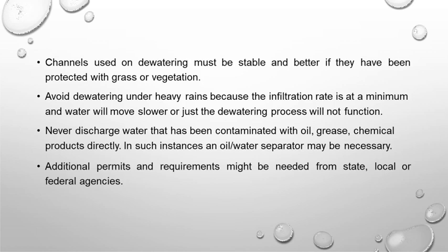Okay, so due to the displacement of the piston, the water is going to be pushed through the outlet pipe, or the delivery pipe, or discharge pipe. During the first stage, it creates a vacuum so that the water is filled into the cylinder. And during stage 2, the delivery stroke, the water is full and the delivery valve opens and water is delivered.